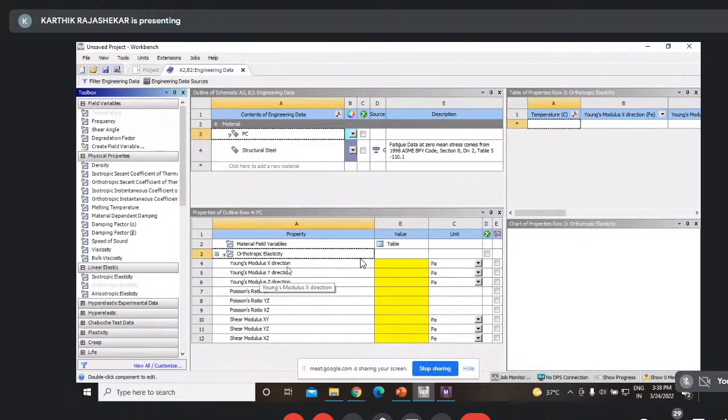Initially, you have the matrix as well as the reinforcement, and you have the rule of mixtures. Taking that rule of mixtures, you need to find out the modulus along x, y, z directions, and incorporate those into this. If you can find these 9 elastic constants, it is applicable, you can incorporate them in the software and do the analysis.